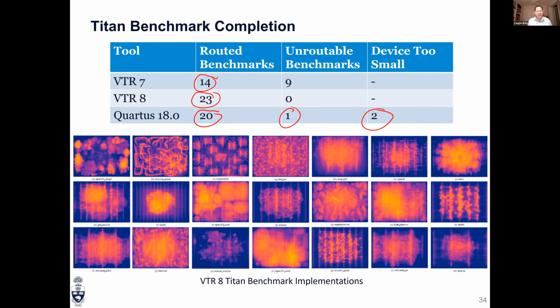And the other interesting thing is that the congestion maps look pretty different for different designs. So it shows that having a diversity of benchmarks is pretty important to tuning your tools. Some of them, like this Bitcoin one, look pretty regular because they're soft logic dominated. But other ones, you can see that it's the hard blocks, which are in columns in the Stratix 4 architecture, that are really changing the nature of the placement problem quite a bit.